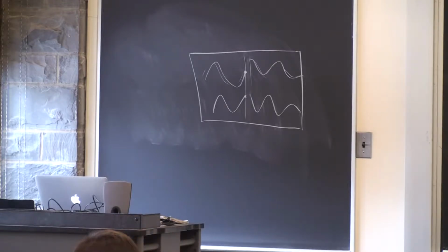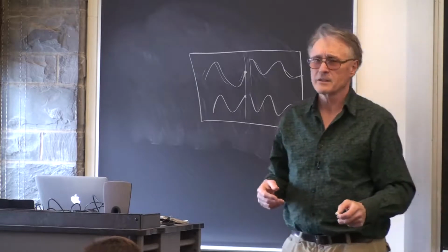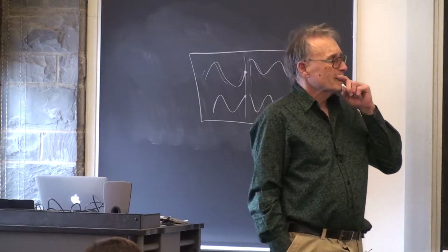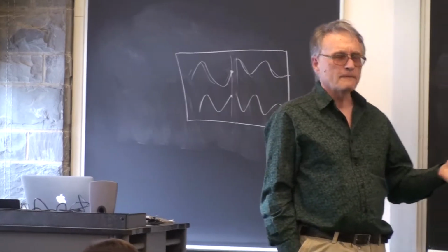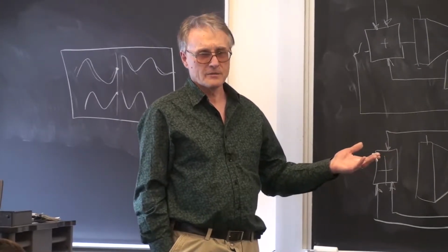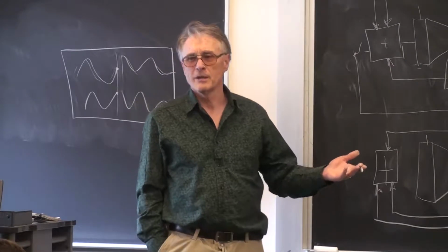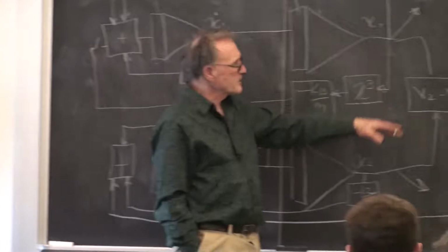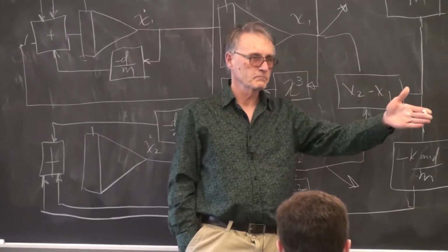This has a big advantage in that you don't have to remember the value for the whole waveform. You just erase everything along that. And it looks kind of like an oscilloscope display too. And all that should be done by the bus master rather than the HPS, right? That's going to be done by the bus master that you write, that takes the output and masters it into the VGA memory.